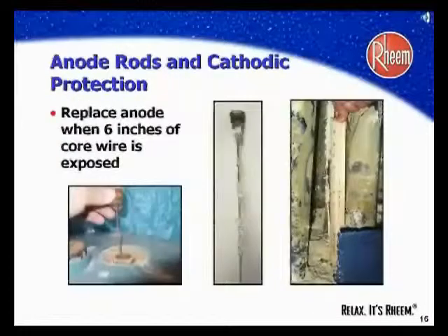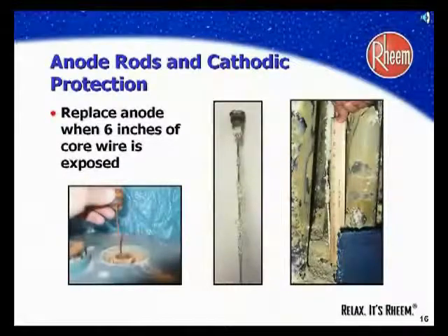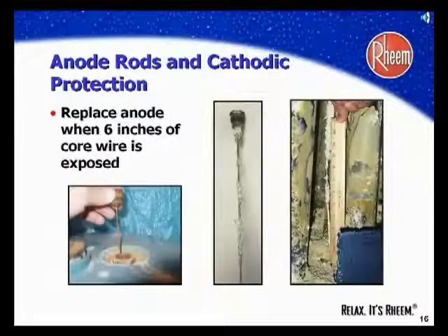The anode rod is a component part of the water heater that needs to be inspected on occasion. If you see 6 inches or more of the core wire exposed, it is time to replace the anode rod.